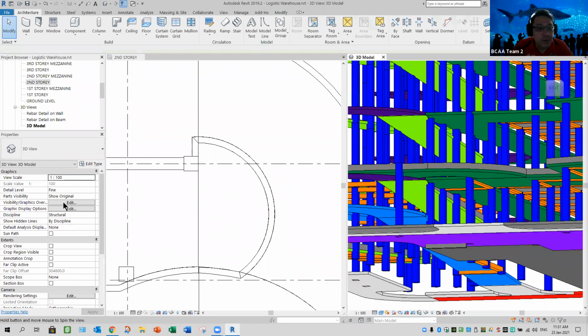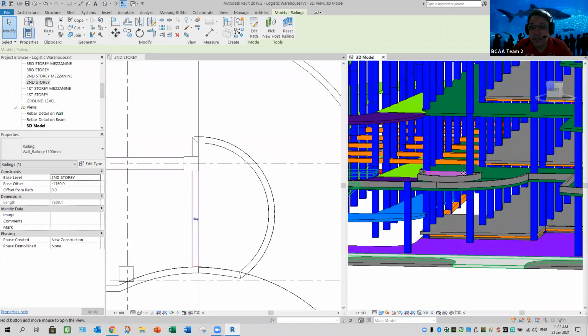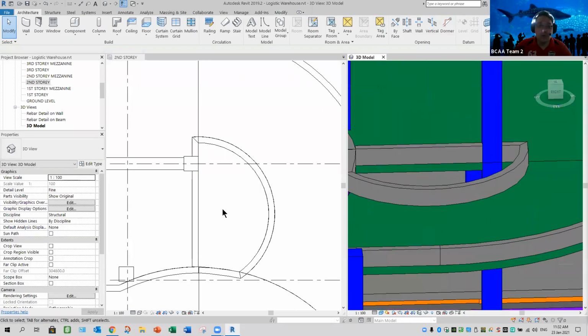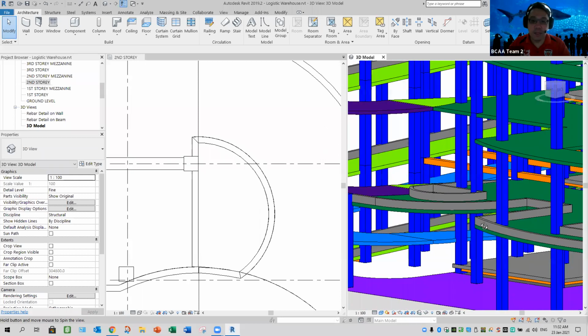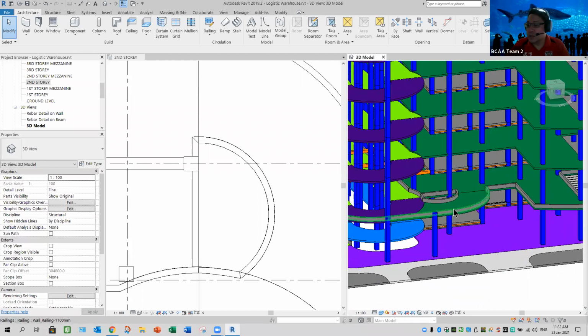It should be at level 2. So be careful. Because when you activate the tools from model, they always go to ground level. You activate the function from the plan, then you stay at the plan. So at least I've created something like this. Then you should regenerate or copy and paste all the way up.